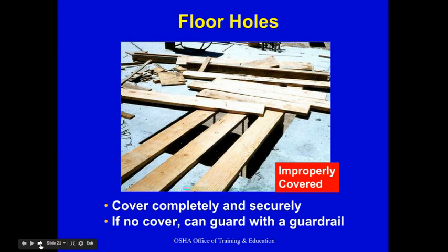Holes in floors, very important. You can see that they've kind of covered this, but they've done an inadequate job because they've left these big gaps here. And those gaps are areas where material or tools could fall down to people in the level below. You could drop a piece of wood, you could kick something. Who knows what would fall down there, and who knows who would be beneath it.